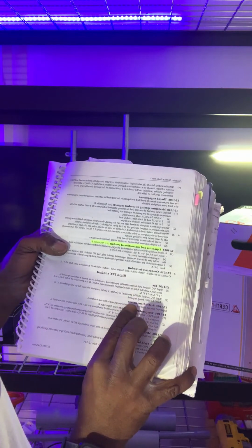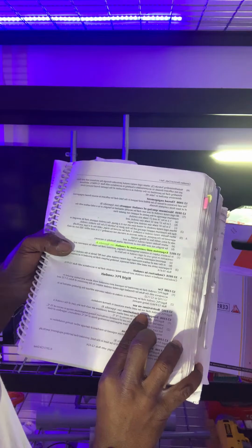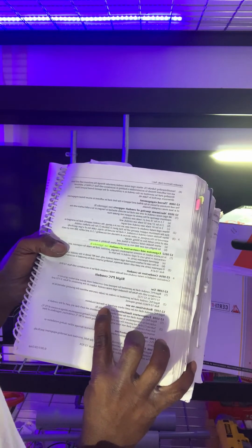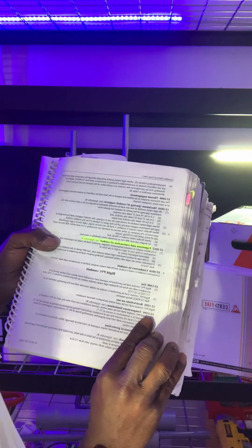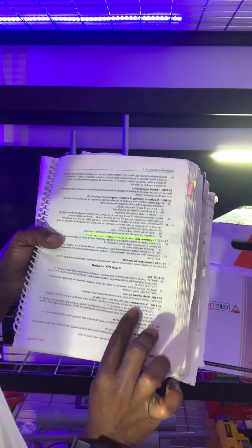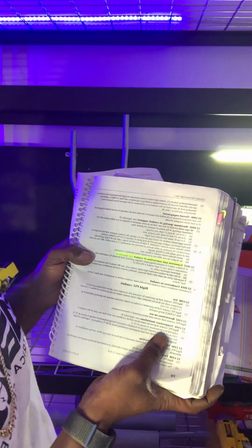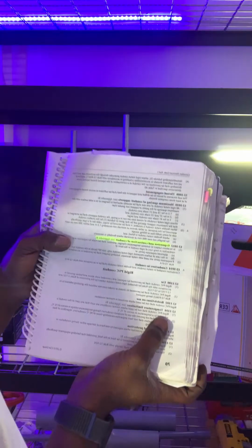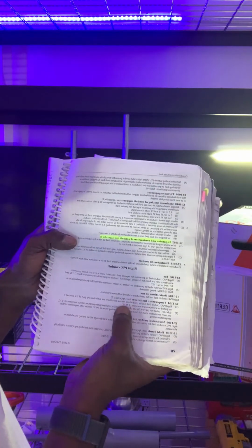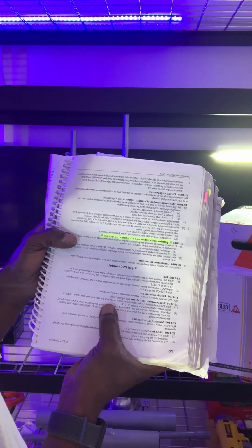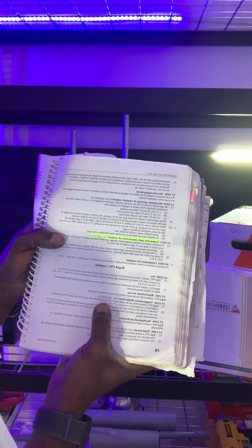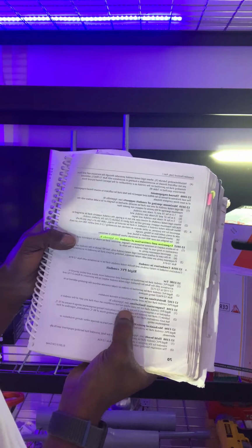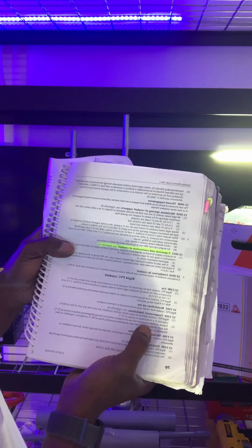Restrictions on use. 12-1102. Rigid PVC conduit shall not be used where enclosed in terminal installation. Rule 12-1104. It says temperature limitation. See Appendix B. 1. Rigid PVC conduit shall not be used where normal conditions are such that any part of the conduit is subject to a temperature in excess of 75 degrees Celsius. 2.